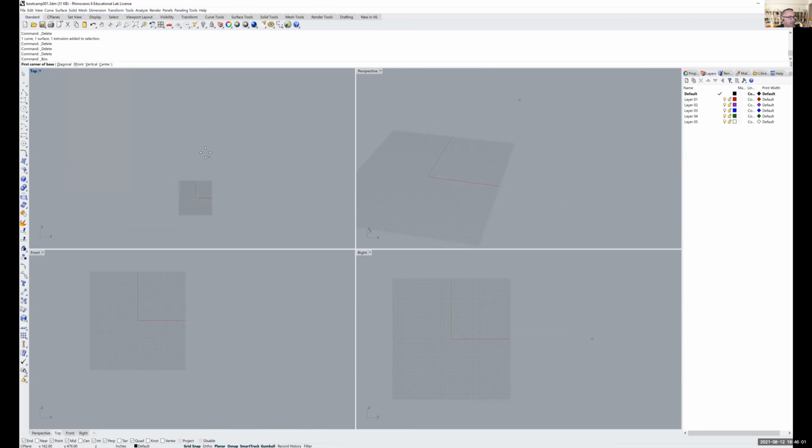And given what Nicholas just asked, maybe we'll start with our box and type 0, then enter as the first corner, and then it wants the next dimension. Let's make this 10 feet. Even though our units of this model are in inches, we can still say 10 with a single apostrophe, which will be feet. So that will set your next dimension. You can even move to a different window. Now we need the other dimension in plan, so we can say 10 feet again and type enter or right click. And now it's looking for the height.